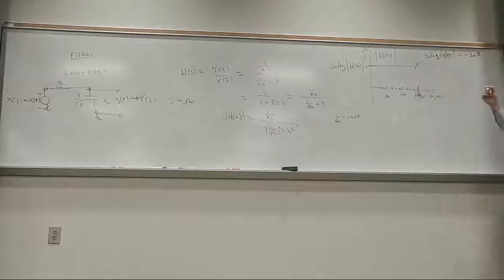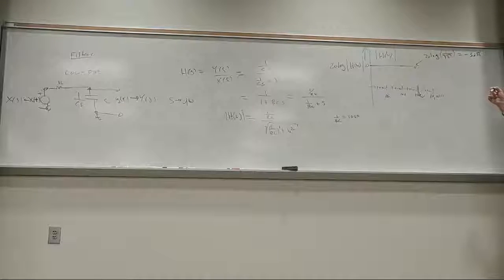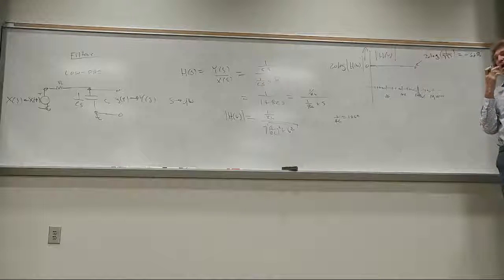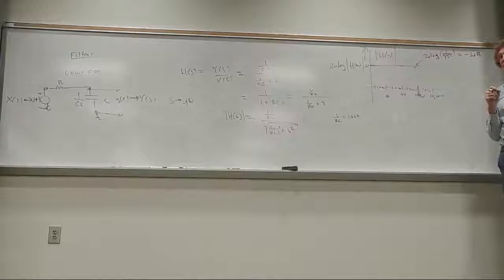If you go ahead and do that, just do this for me. Take the log of 1 over the square root of 2 times 20. It's really 10 times the log of 2, minus 10 times the log of 2. It's about minus 3 dB, I think. Y'all see that? Is it 3 dB? Was it 3.1 something? All right, it's minus 3.3 dB.